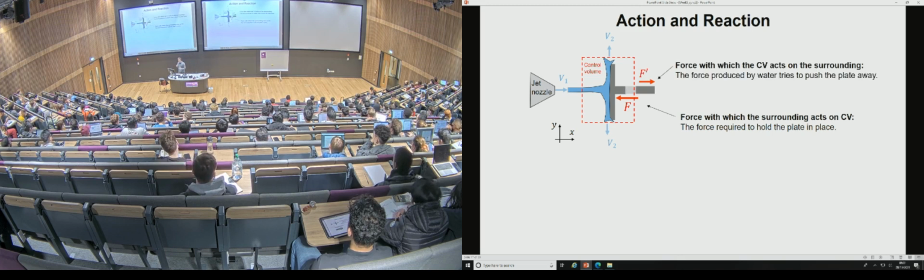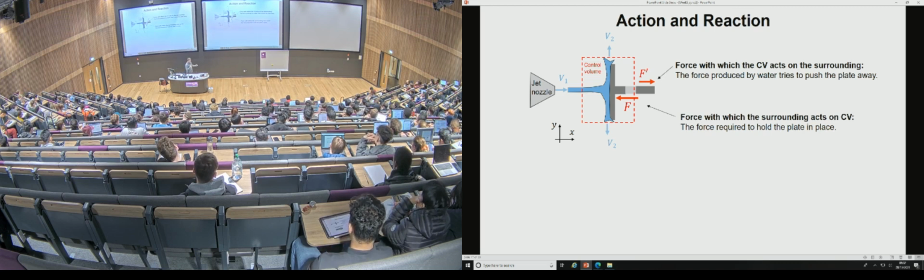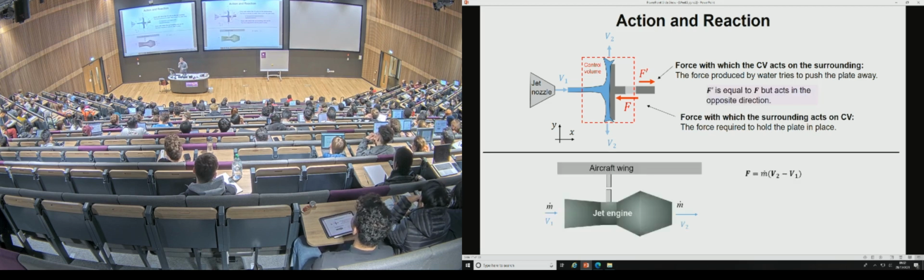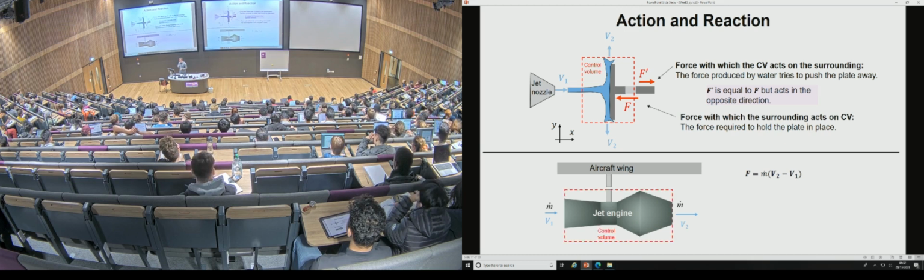There's a reaction that's outside the control volume, felt in order to keep the structure stationary, and that is the force in the reverse arrangement, the water acting on the plate. Equal and opposite, unless you're told otherwise. The classic example, like I mentioned before, is propulsion. So whether it's a rocket or a jet engine in a test bed, the same thing applies.